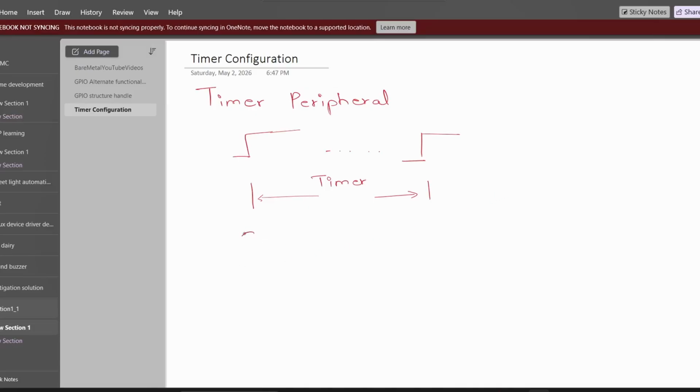If I want to calculate frequency, this is a classic example, then I'll need a timer. Timer peripheral can also be used as a counter. So how many pulses have occurred on a GPIO pin during 1 second, we can calculate using timer or counter, and the inverse of that we'll take as the frequency. So we can use the timer as a counter also. There are multiple uses.